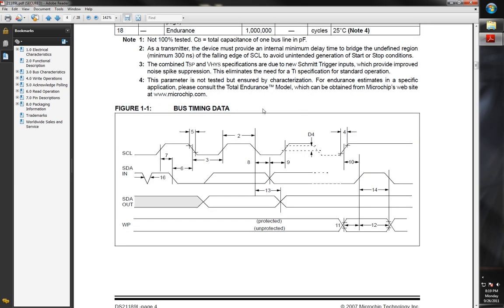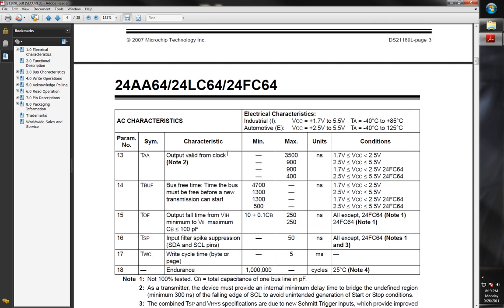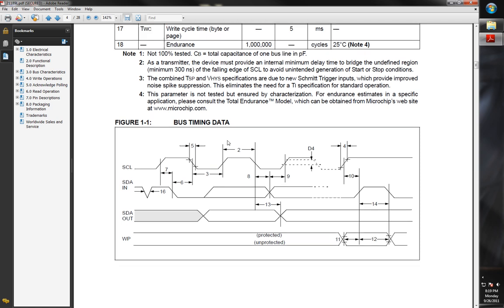That's another thing that is great about the CCSC compiler, which we'll see in the coding section. They've pretty much already written all this for you, all the handshaking and acknowledgments and everything that goes between the program and the I2C bus protocol. This is all taken care of for you by the CCSC compiler.